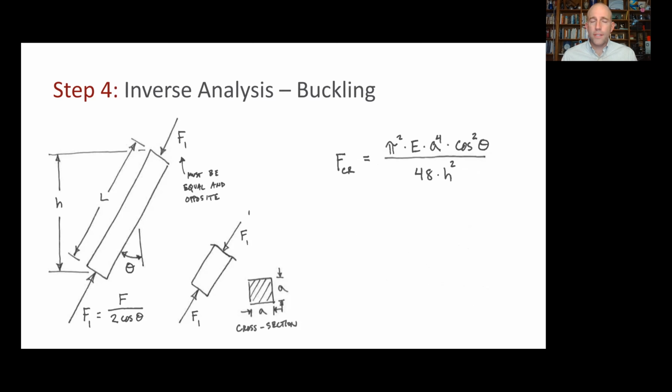Okay, now let's do the same thing for buckling. We're going to substitute in something with a factor of safety for a critical force, and then solve for one of the parameters that's nice and directly related to part mass. So do that independently, then with a partner, and then come back. It should just take 3 minutes or so. You can hit pause now.